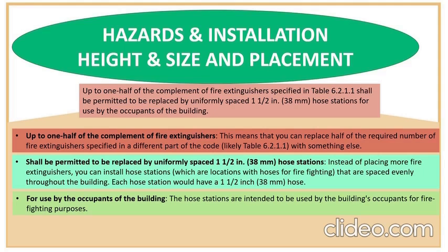So when you provide water firefighting hose stations, you reduce the number of fire extinguishers, for example. When you install firefighting hose stations, you can reduce the number of fire extinguishers in half, which means you can place three fire extinguishers to cover the remaining areas.